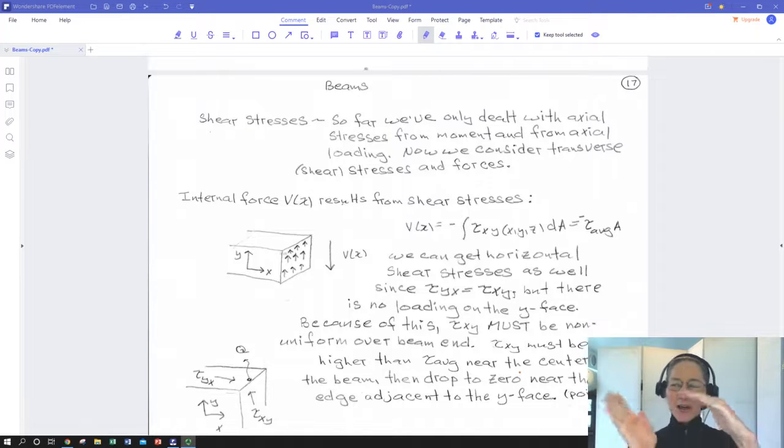Now we're going to literally turn 90 degrees and look at what is going on in terms of shear stresses. So this is harkening back to our big V as a function of x along the beam, which is our shear force. Basically, we're looking now at forces perpendicular to the direction of a position along the beam, or parallel to a cut face that we would make if we're analyzing the beam.